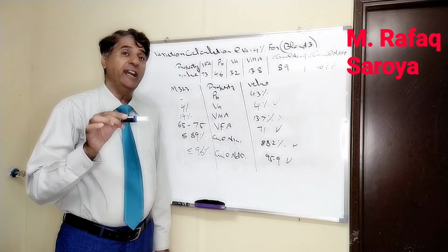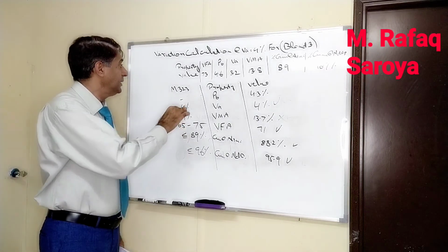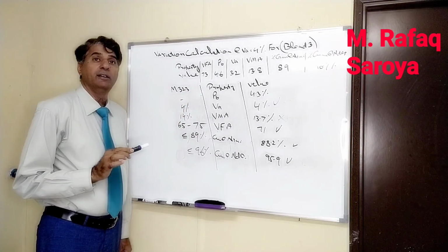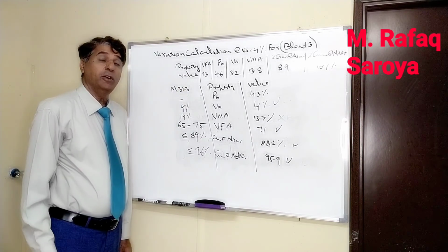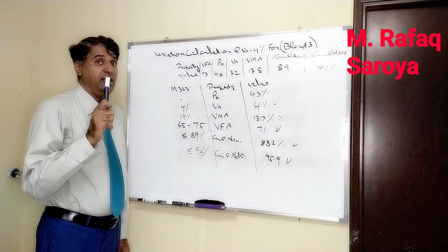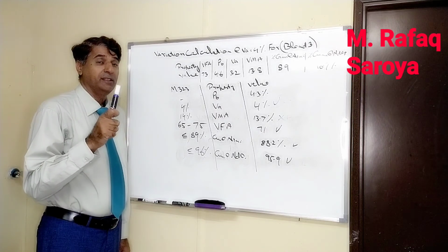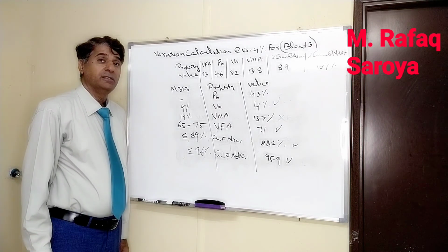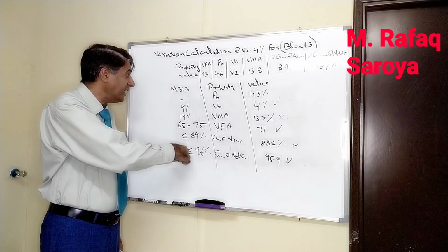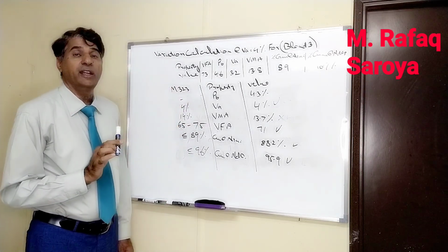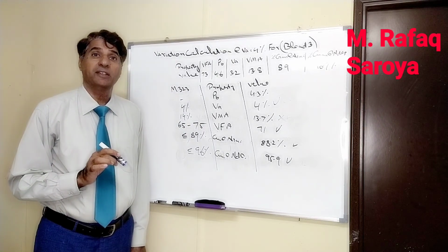But blends 2 and 3 fail to meet the specification criteria given in the AASHTO M323 specification. There is only one blend, our blend 1, which has satisfied all the requirements given in the Superpave specification.